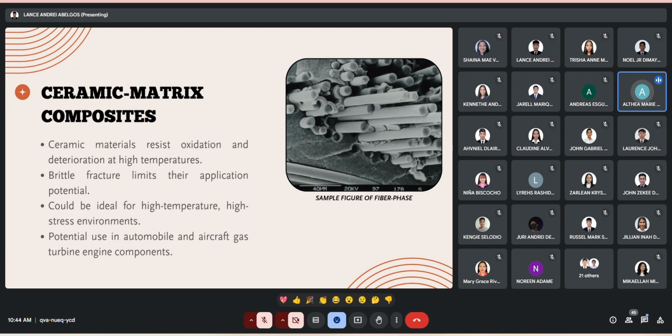One particularly interesting toughening technique uses a phase transformation to arrest the propagation of cracks and is aptly termed transformation toughening. Other recently developed toughening techniques involve the use of ceramic whiskers. Ceramic matrix composites may be fabricated using hot pressing, hot isostatic pressing, and liquid phase sintering techniques. Next slide po.